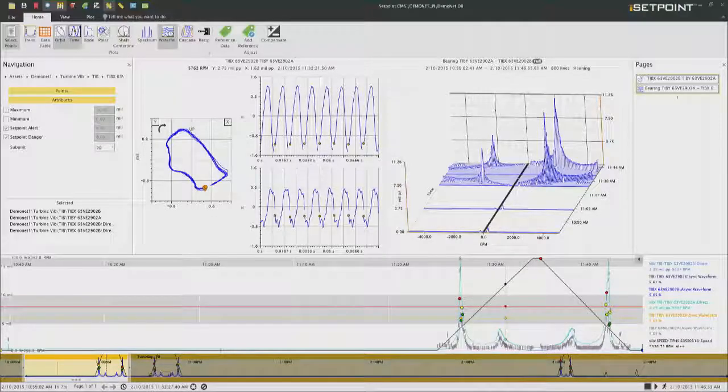So essentially, all through here, because nothing interesting was happening, we didn't have to send any data to the Pi system in terms of waveforms, because nothing interesting was happening. The waveform, for all purposes and intents, right here, was the same as the waveform here and all the way through here. But notice, as I start to ramp the machine speed up, here's my vibration amplitude.